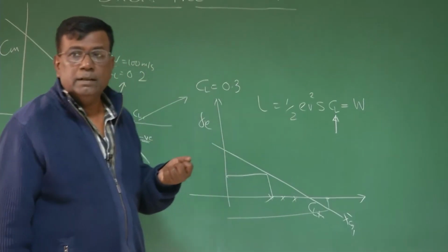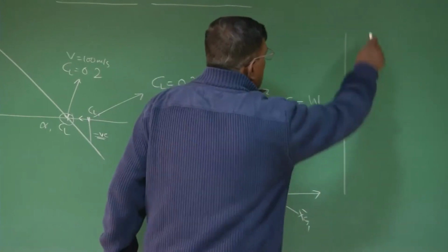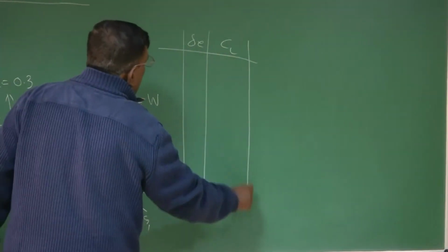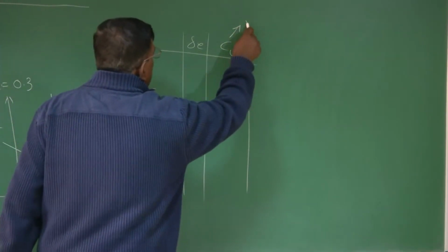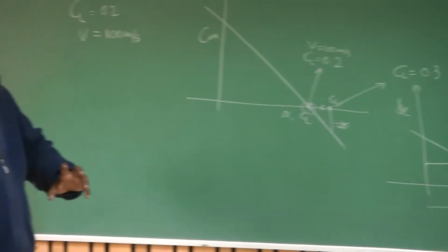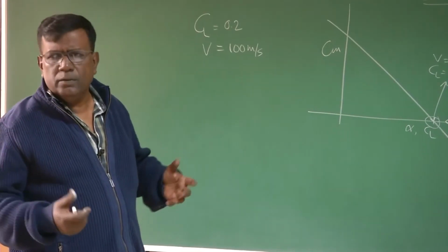How will he fly? So, one way is you make a chart of delta E and CL, or CL means you can always relate to speed by giving density, and he sees that chart: oh, for this much V, I will put this much delta E. Or sometimes, for giving delta E there may be a rotating shaft, a wheel, he can rotate this; many combinations were there.